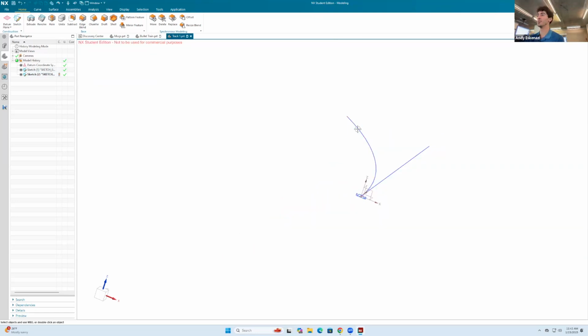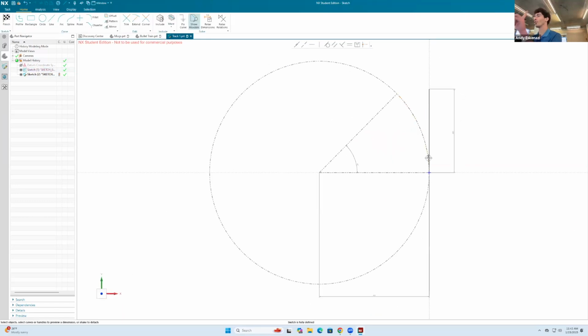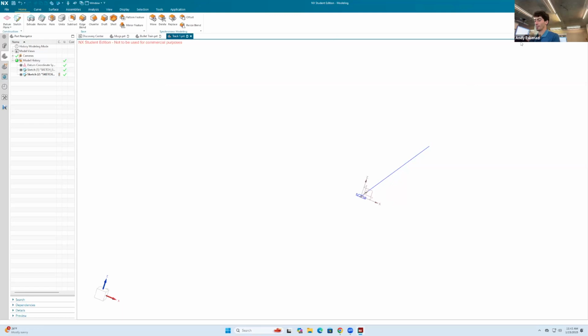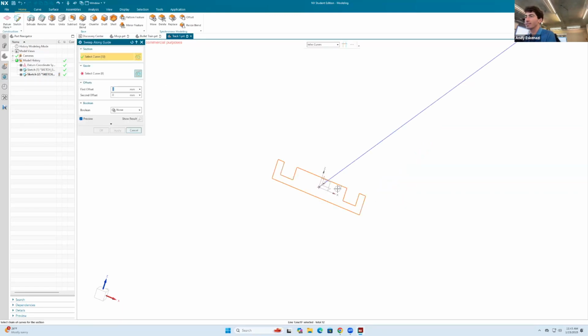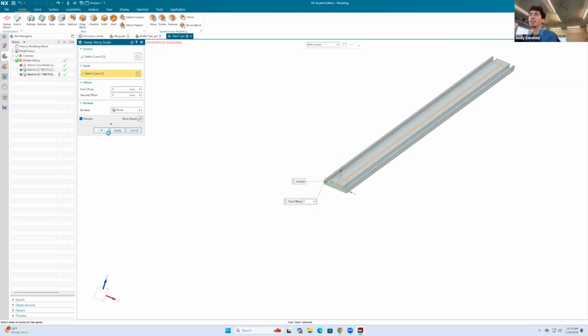Actually, there's one thing I should do. I'm gonna edit this one. I will make that construction for now, and I'll save it up in a moment. But I go here to swept, swept along guide, here, boom. I say, okay.